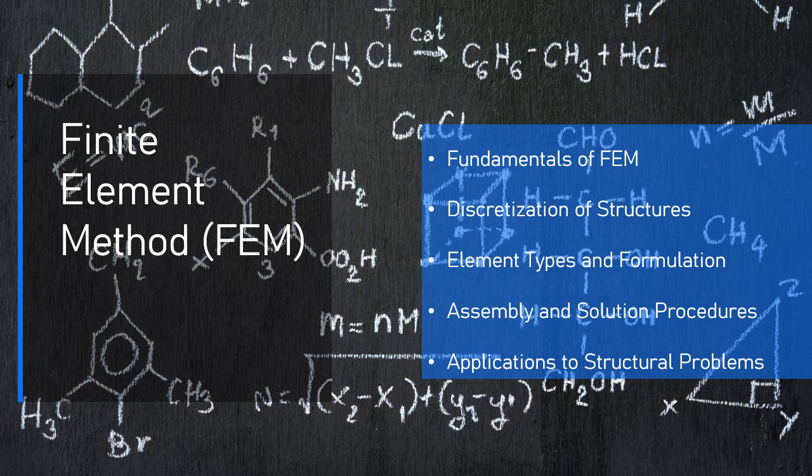4.1. Structural analysis of beams and frames. 1. Beam analysis. FEM can be used to analyze beam structures under various loading conditions, including uniform loads, point loads, and moments. The method provides a way to evaluate deflections, bending moments, shear forces, and stress distributions in both simple and complex beam geometries. Application example: a cantilever beam subjected to a concentrated load at the free end.